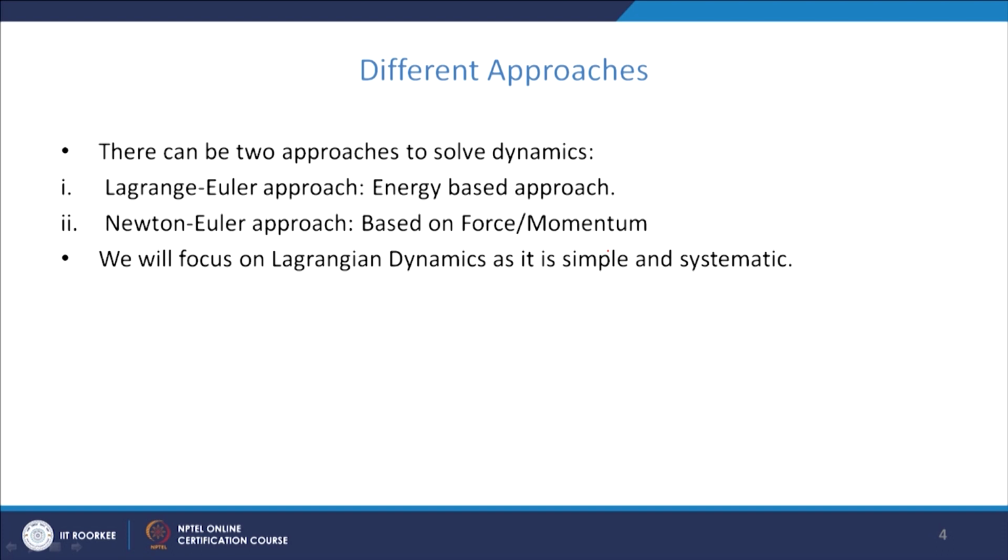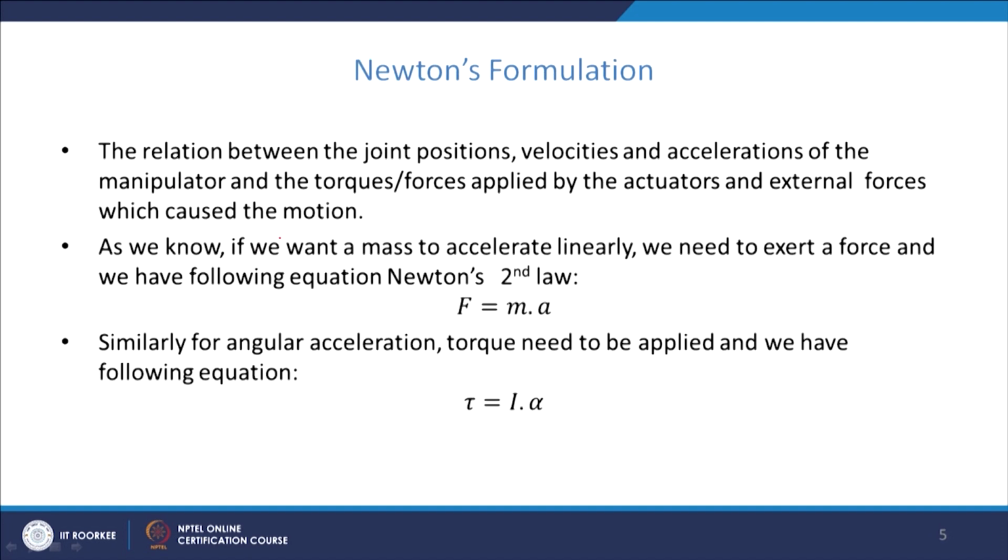So, to formulate the dynamic equation, there are two approaches. One is the Euler-Lagrange approach, which is an energy based approach, and another is the Newton-Euler approach, and it is based on the force and momentum of the manipulator. So, in this lecture we will concentrate on the Euler-Lagrange method.